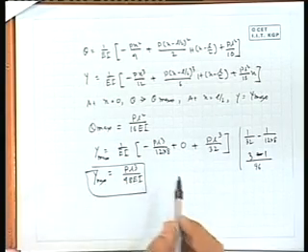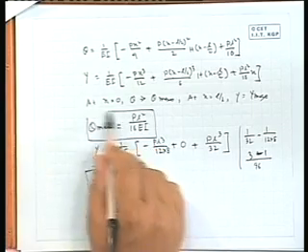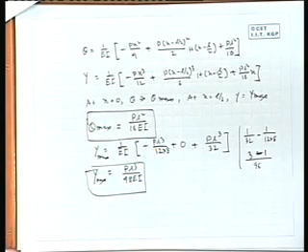Now this is one of the very standard forms: y max is PL cube by 48 EI, and theta max is equal to PL square by 16 EI. So, by this time we have found some standard expressions: for a beam fully loaded, the maximum deflection and maximum slope we get, for a beam with a central load, these values, and for a cantilever we got some forms.